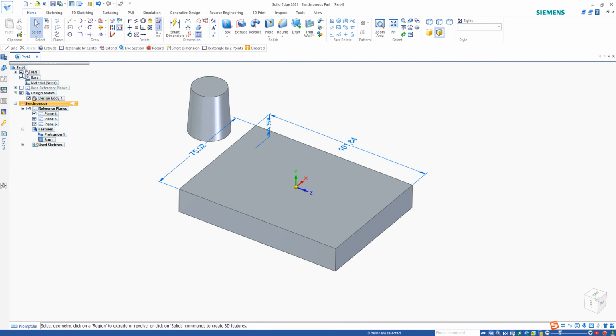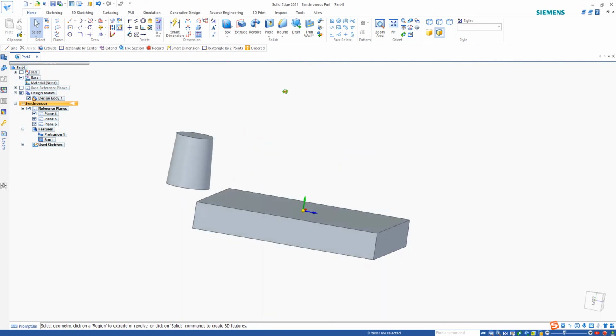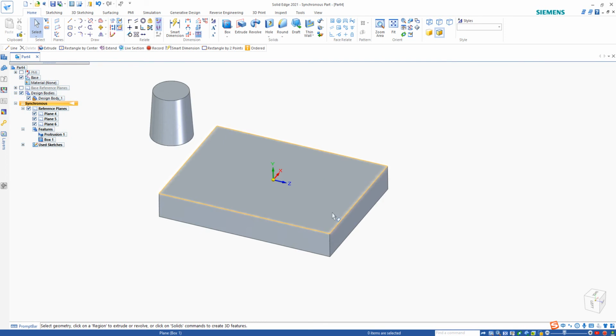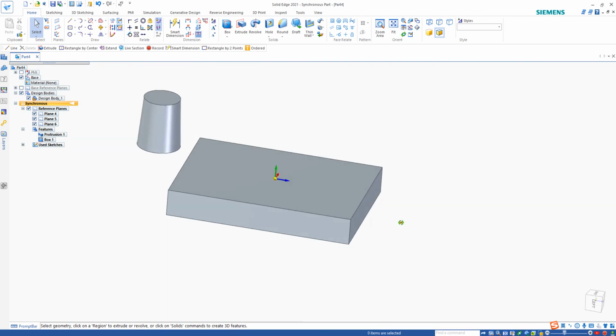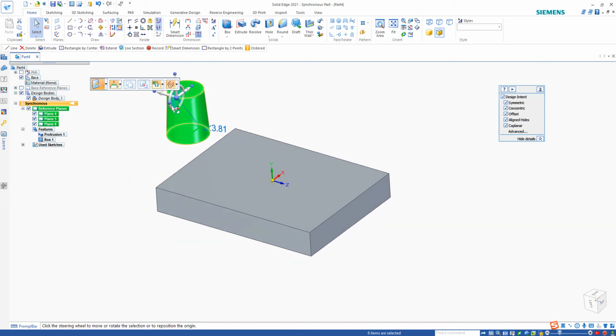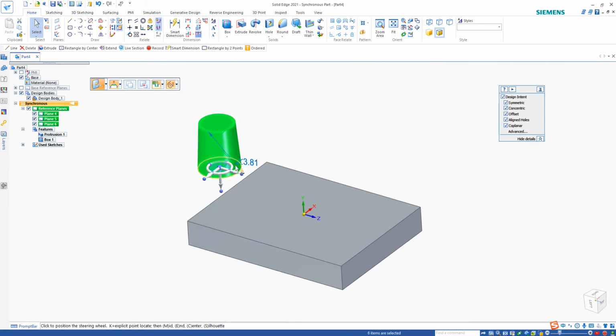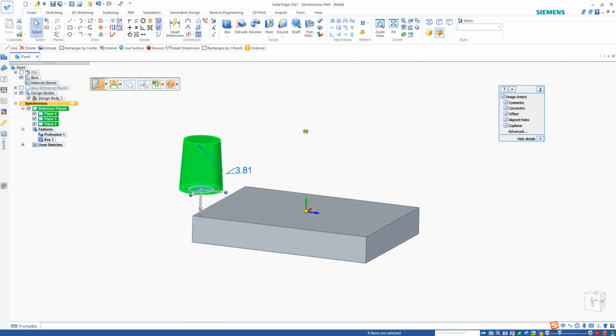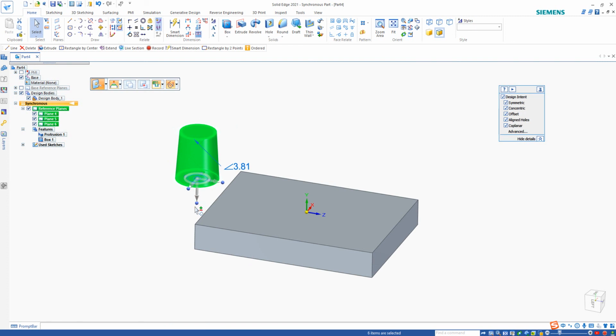Okay, say I want to move this conic body to the edge of the plate. How can I do that? First, you want to select this body, and when the steering wheel appears, move this to the bottom center. Now you want to pick these small balls at the end of the handle and right click, and have it point to the edge, the vertex of this corner.